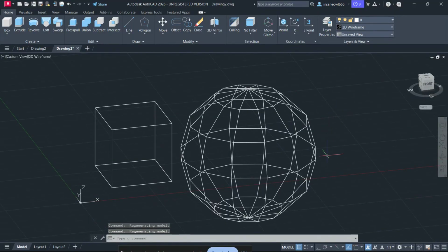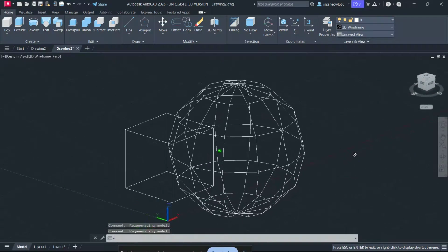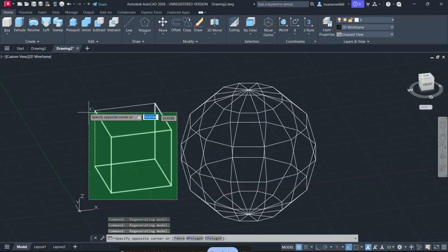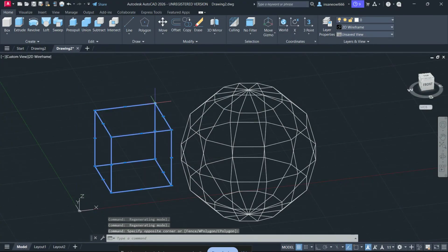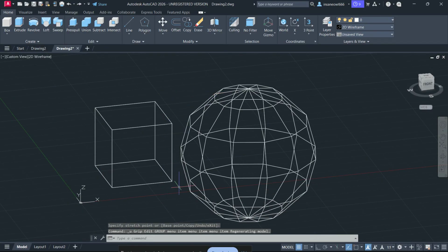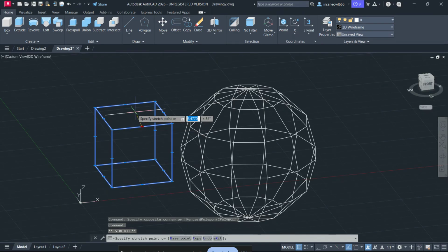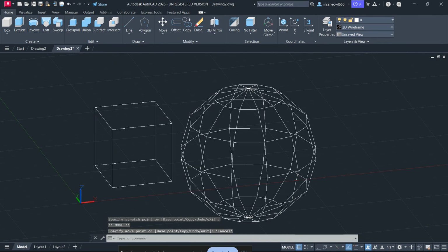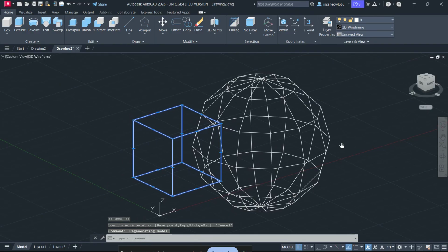The first and often easiest fix is what I call the micro move. Select one of the objects and move it by a tiny amount, like 0.0001 units. This tiny shift can break the problematic edge alignment and give Autodesk Shape Manager a cleaner geometry relationship to work with. After moving it, try the boolean operation again. In many cases, that alone is enough to solve error code 97012.